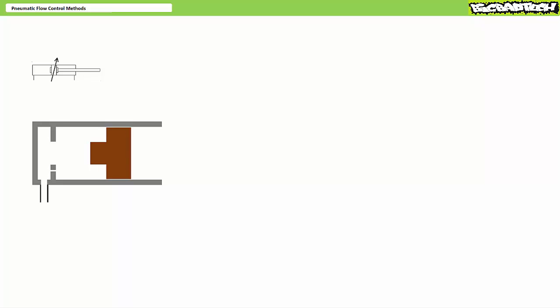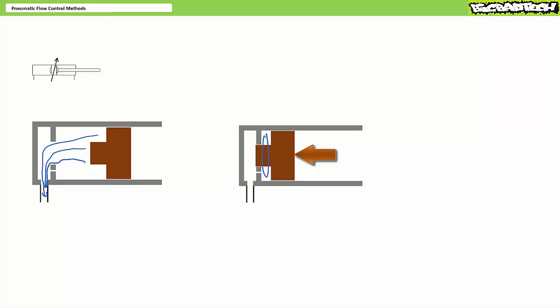Cylinders with cushions have a special shaped piston with a plug that fits into a circular depression. Here I'm illustrating a cushion on retraction in the cap end with the rod omitted for clarity. As the piston retracts mid-stroke, the plug and hole don't come into play, and exhausted air has an unobstructed path out of the barrel. However, as the piston nears the limits of retraction, the plug fits into the hole, blocking the larger port, leaving a cushion of air trapped between the piston and the ring, with a narrow restriction as the only means for air to exhaust.